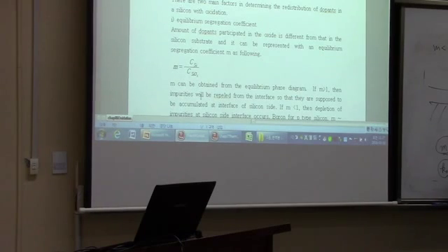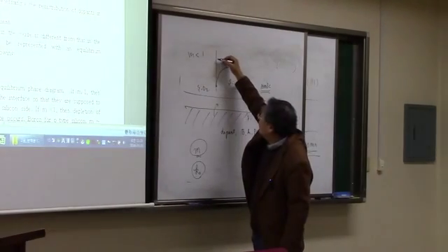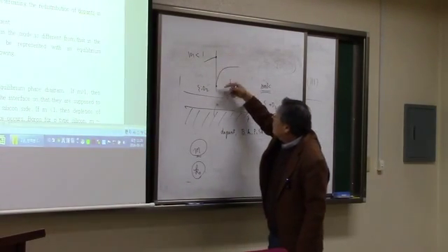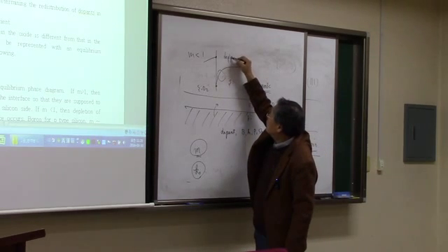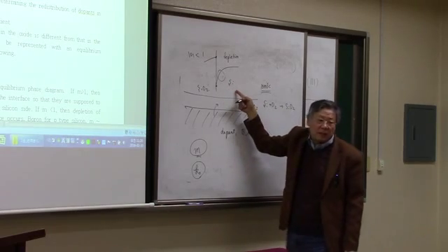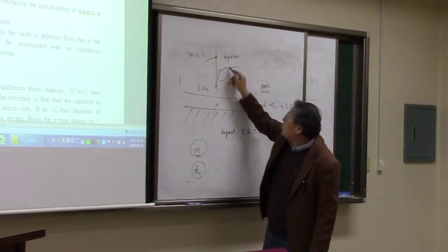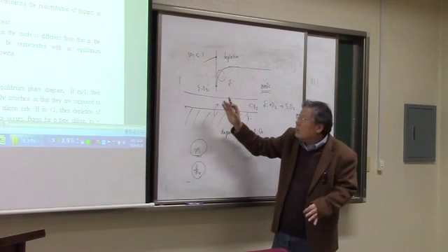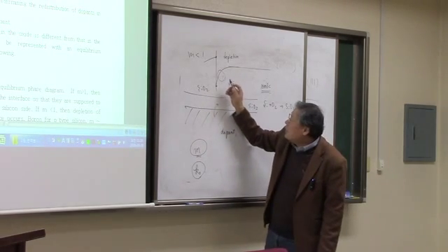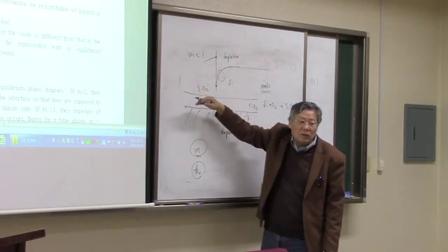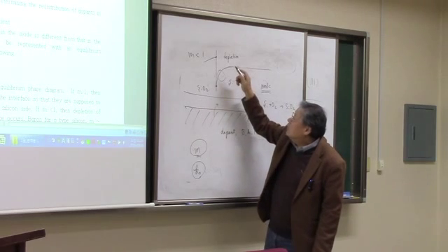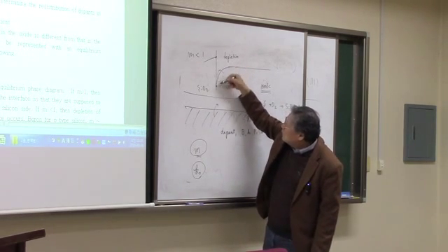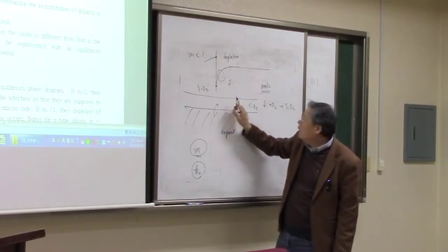then we are going to have depletion of the dopant atoms. This is the silicon and silicon oxide. And if M is less than 1, then we're going to have depletion of dopant in the silicon. Originally, before the silicon oxide, we have this much dopant concentration, and by growing the silicon oxide on top of the silicon, the dopant atoms are going to be incorporated into the silicon oxide, so that there is going to be some depleted zone, like that.